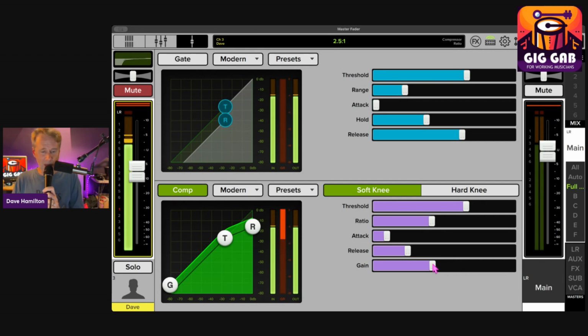You will adjust the makeup gain to sit right at about that 0 unity point when someone is talking. If you're looking at the video, if I'm talking quietly like this versus talking really loud like this, there's probably a 15 dB gap on the input and only maybe a 4 or 5 dB gap on the output.